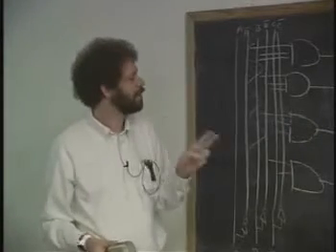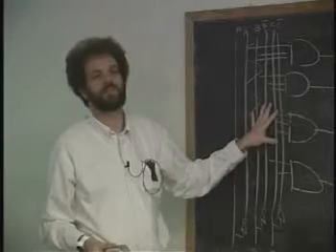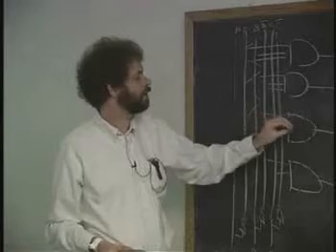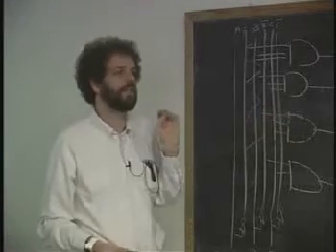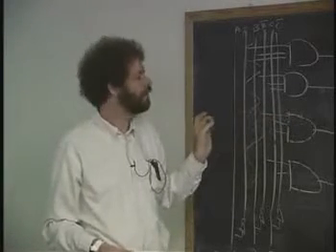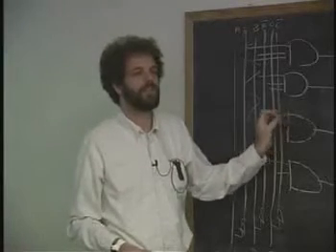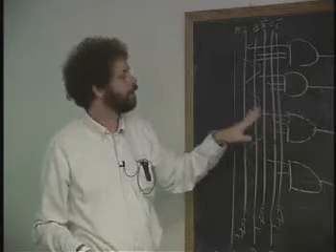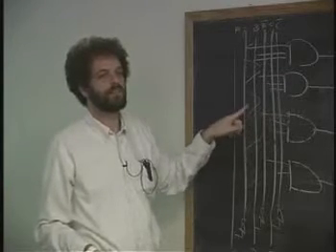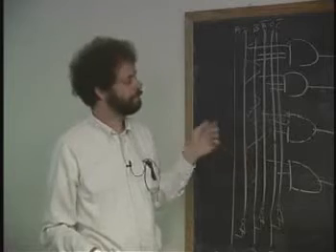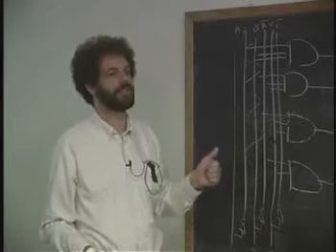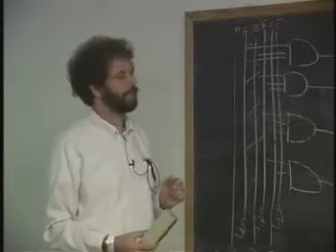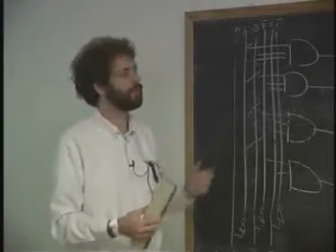Two really awful things. A lot of those AND gates are hooked up to the same wires. And it turns out, and we're going to talk about the physics of this, that the electrical characteristic of these AND gates loads the wires just a little bit. Sensing the 1 or the 0 on a wire involves transferring a little bit of charge into or out of the AND gate. And if there's 2 to the 31 AND gates with a lot of them on the same wires, there's a lot of charge that needs to go in and out. And what does that mean? A, the amount of power you need to do that is very large, and B, it's really slow. Because if you supply the charge at a fixed rate, the amount of time it takes to charge them all up is a long time.